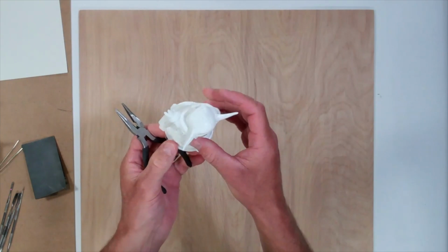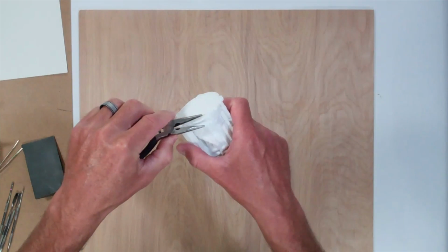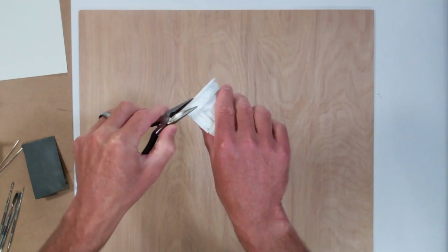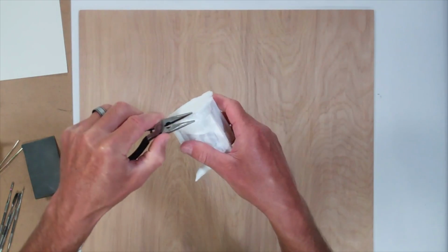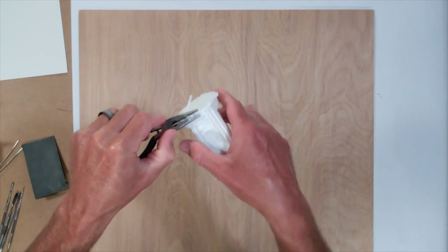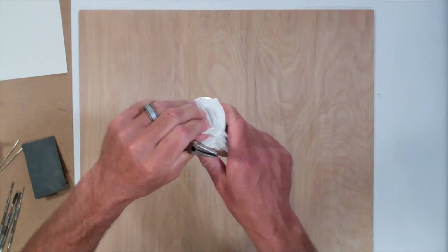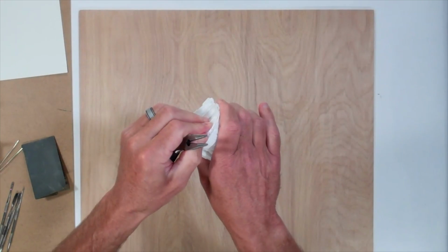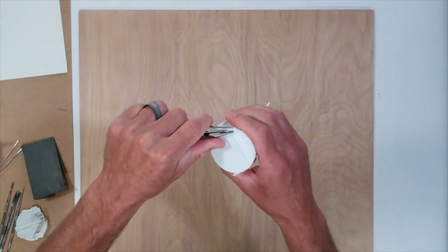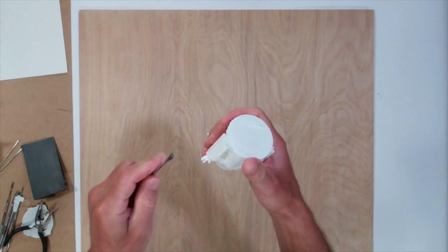So when you get your print off of the bed, if you have a raft, you're going to want to take that off first with some needle nose pliers. Just take your time, be very careful. Go around the edge. You don't want to pull off something that's part of the model. And once you've gone around a couple of times, it should let go pretty easily. Any filament that's left on the bottom of it, you can just use needle nose pliers or some of these modeling tools to very carefully clean those up.